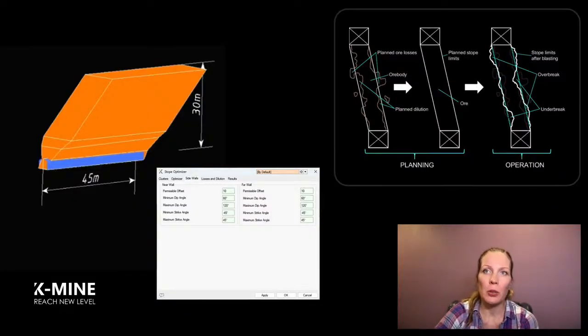We don't first build an economically ideal shape and then throw out the fracture zones. Instead, we tell the optimizer straight away that in this direction, the allowable span is no more than, say, 12 meters, and down deep no more than sublevel height. Then the subsequent optimization methods operate on physically possible objects.